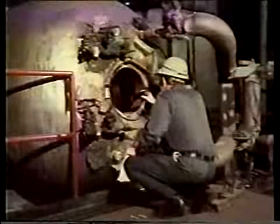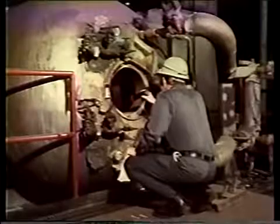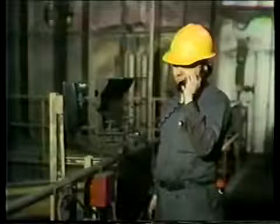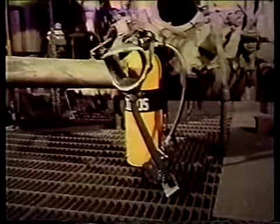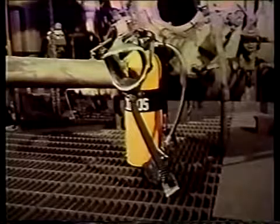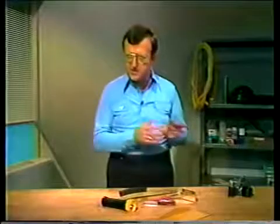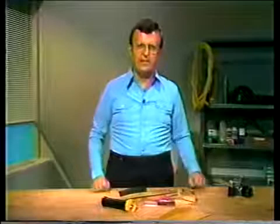Even if it's safe to go inside, be sure there's an observer at the entrance. An observer must be at the entrance whenever anyone enters the component. In an emergency, the observer sends for help. A self-contained breathing apparatus should be available and located just outside the boiler in case there's an emergency. Even under normal conditions, though, there's something the observer must do. Make sure that everyone who goes inside the vessel comes out before the boiler is closed up.